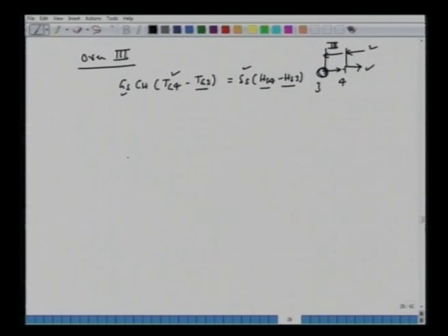So we follow the same approach we had before. How we can get HS4? Let's write down the expression for HS4. HS4 would be CPS, same expression, which is 0.96 plus moisture content 0.0101 multiplied by specific heat of water, 4.187 into this temperature, so 60 minus 0 degree. That's the reference temperature. So now this is the enthalpy at number 4 here. Here we know the temperature 60 and we know this moisture content 0.0101. So which means we can calculate this quantity HS4 here.